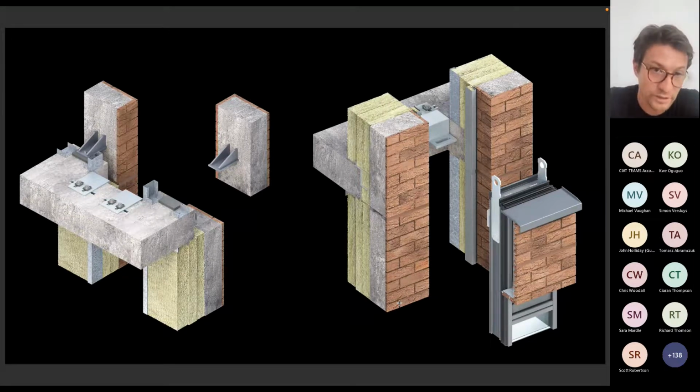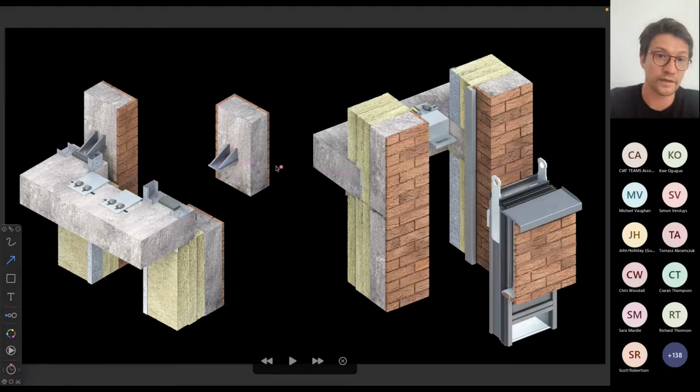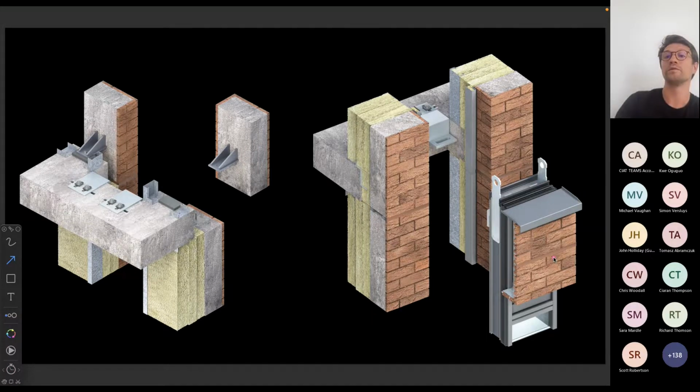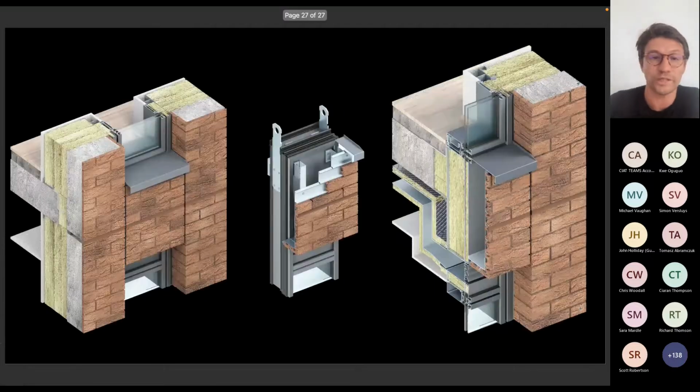In certain areas, that would be installed with a precast bracket and a tie, as we see here. But to achieve a certain fenestration outlook, and to avoid the requirement for access from the outside, one would also use a unitized facade assembly in some locations, like we see in the details here.